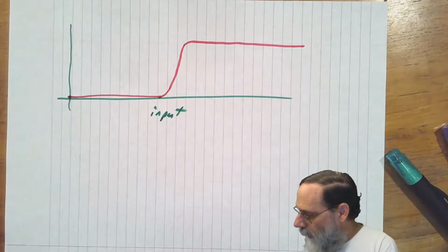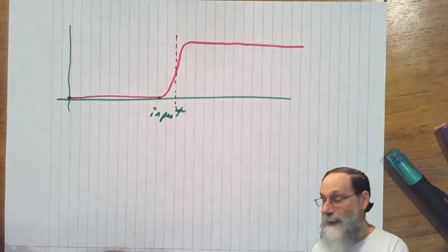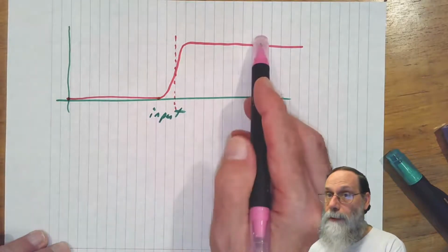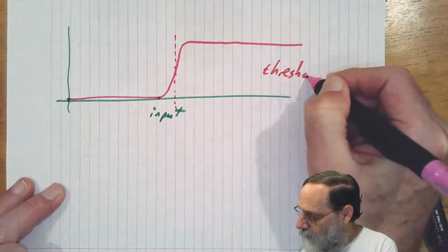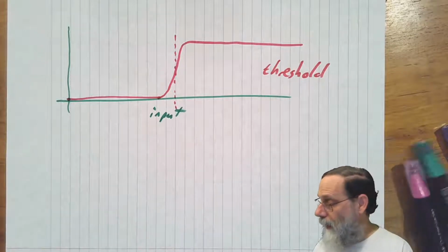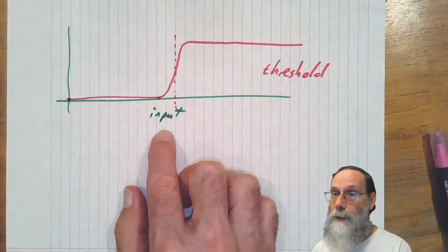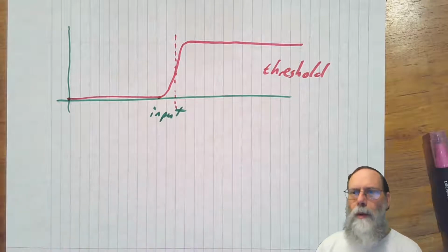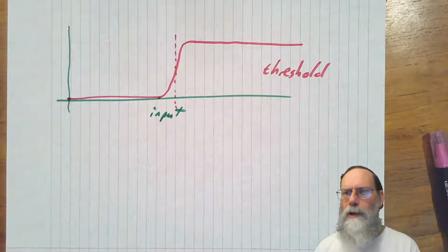Okay, and so there is a particular voltage here, or temperature, particular input value of whatever the input is, at which we make a transition from off to on. And so that threshold makes this a single threshold system. And it's a very simple system. You just compare what your input is to what your threshold value is to determine whether you turn on or turn off. What's the problem? Well, what happens if the input measurement is noisy?